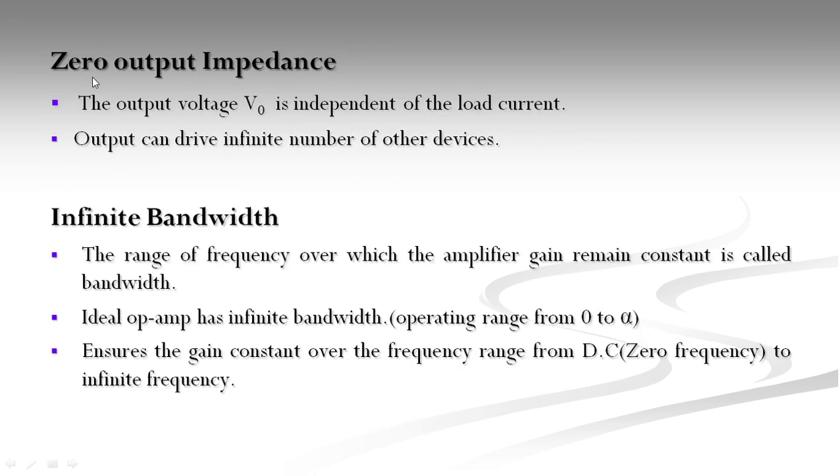And the third one is zero output impedance. Since the ideal op-amp has a zero output impedance, the output voltage V0 will be independent of the load current, so the output can drive an infinite number of other devices.